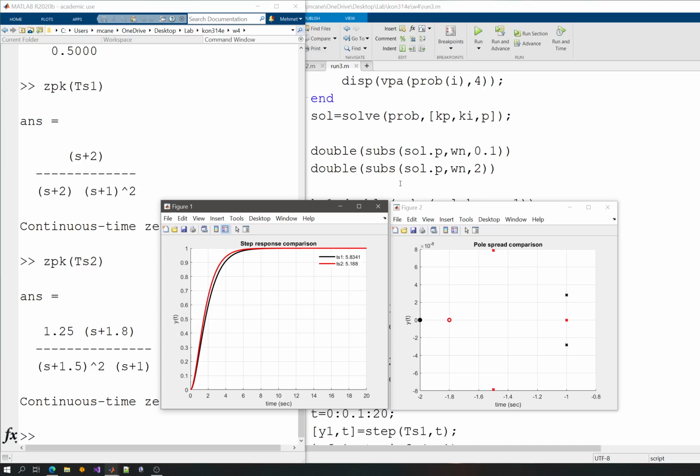We will decide if we can directly assign the poles, if it's a second order system. If it's a first order system, it's also possible to directly choose a pole there, and then some other characteristics maybe can be taken into account. But if we have a high order system, our approach will be to use the dominant pole placement. And during this dominant pole placement, we will have some parameters.